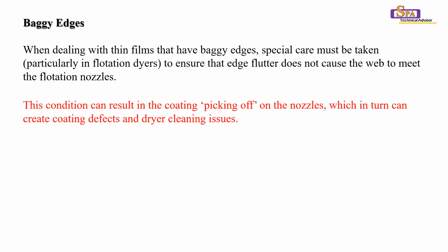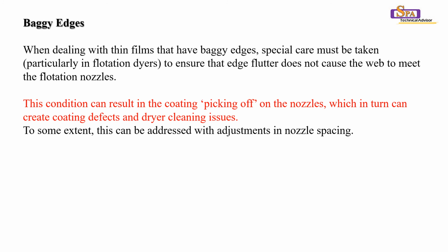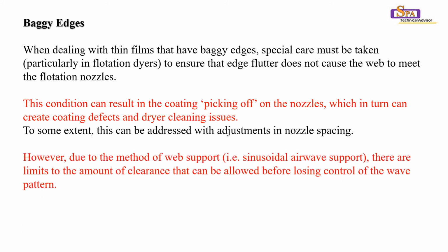Baggy edges. This condition can result in the coating picking off on the nozzle, which in turn can create coating defects and dryer cleaning issues. To some extent, this can be addressed with adjustments in nozzle spacing.